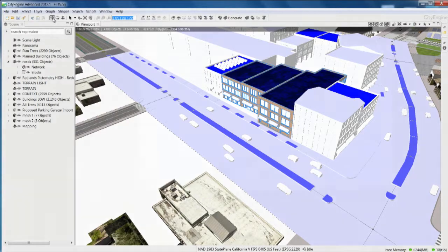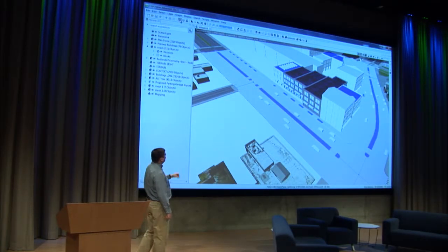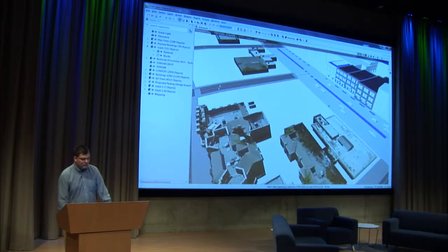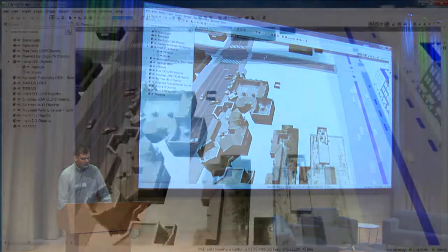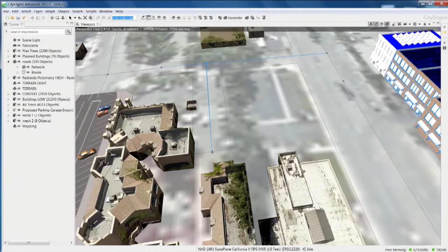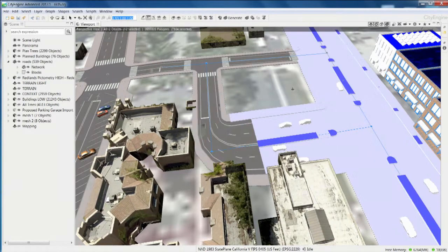Now what I've shown here is creating from street center lines, creating buildings from footprints, creating buildings from parcels, but this is actually also an interactive creation tool. So we can go in and create new features. I'm going to go ahead and create a new block. We have this empty area here. I'm going to start creating a street. It grabs the attributes from the first street, and then it's going to grab the attributes from the second street, which is going to be a little wide here. So now it generated new streets. Turn the models off, and I can see this block.